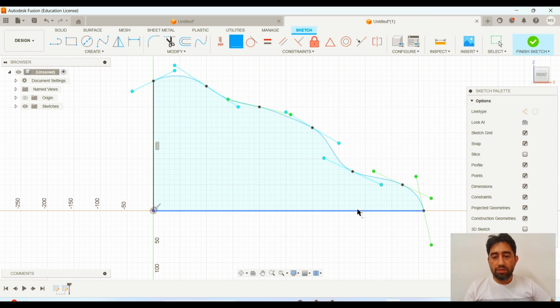These vertical and horizontal lines are black, and this line is not black because it has so many control points, 1, 2, 3, 4, 5, 6, 7, and their handles, both of which are to be given some dimensions so that it can be fully defined. The control handle length as well as orientation is necessary to define it, as well as the position of these control points.